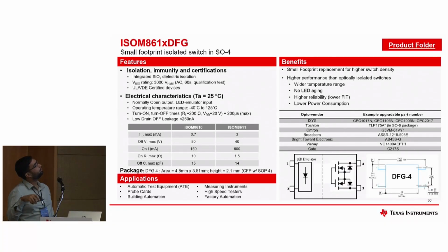And C off. Whenever you use this kind of devices, generally these are multi-node connections. So you have the same line going through, touching different nodes of these devices. So the off-state parasitic capacitance becomes important in high-speed applications.